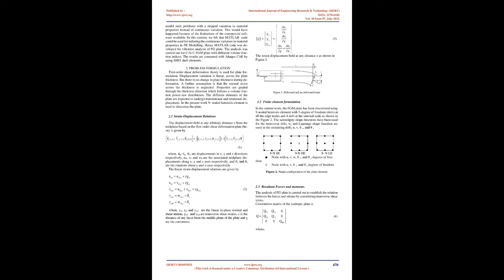They have developed analytical formulations and solutions for the free vibration analysis of functionally graded plates using higher-order shear deformation theory, HSDT. The principle of virtual work was used to derive the equations of equilibrium and boundary conditions. Navier's technique was used to obtain the solutions for FGM plates.